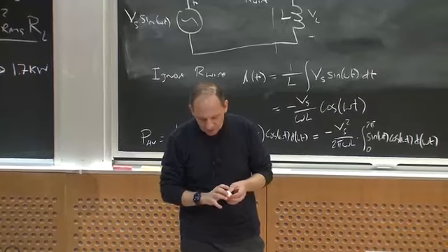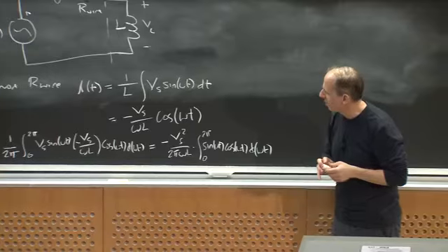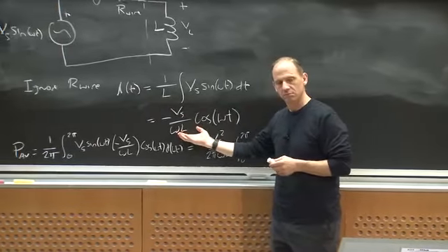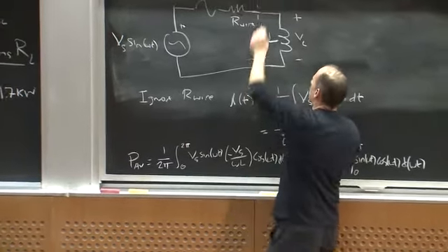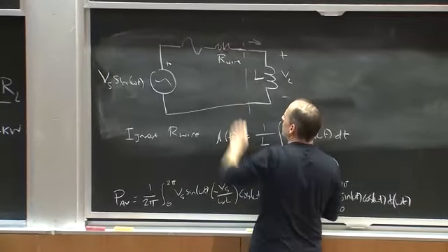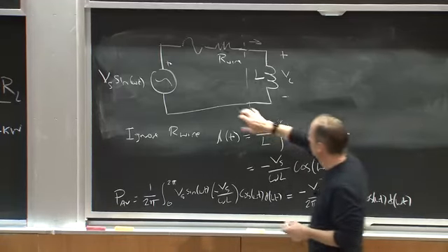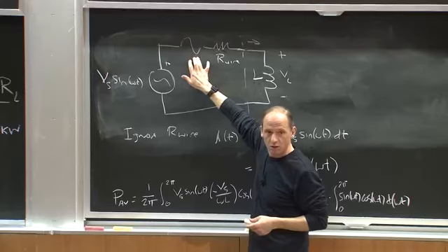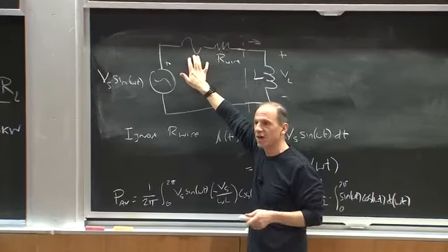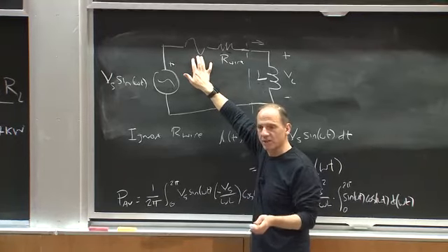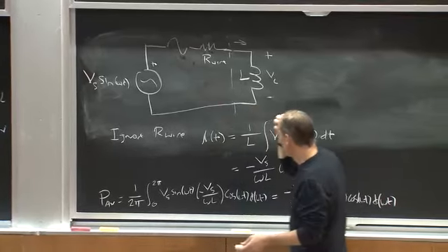So that makes sense. But notice that while I'm drawing no average power, I still have current, right? And that means I am still dissipating some energy in that wiring resistance, and I'm still limited in the current I can draw before the breaker goes, or before the fuse pops, right? Because the fuse or the breaker is designed to pop based on, in the long term, RMS current, okay? So what does that look like?